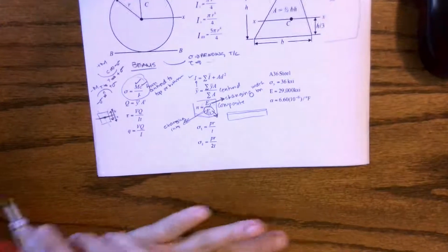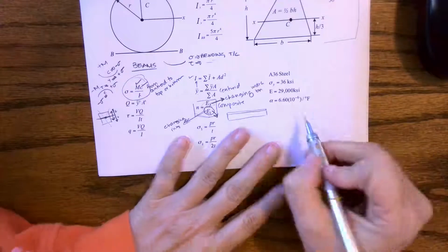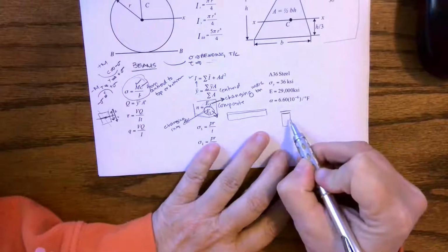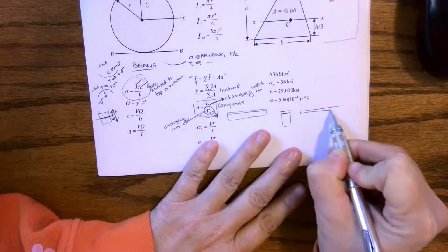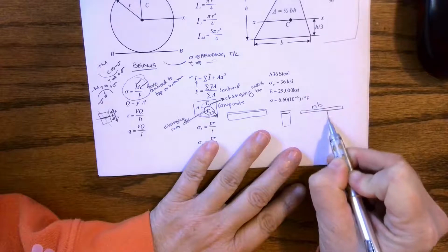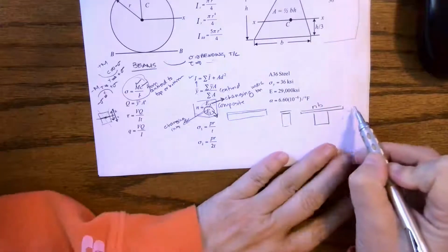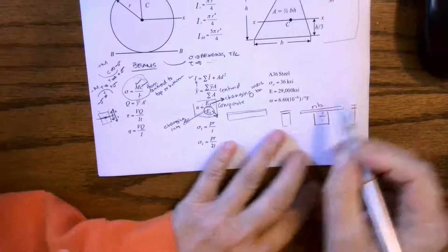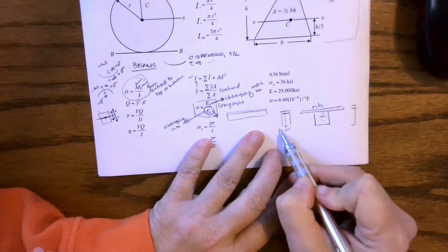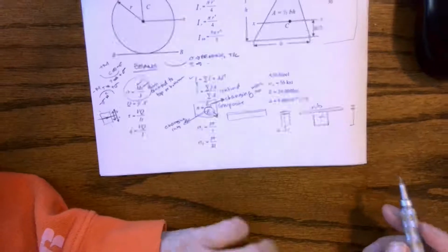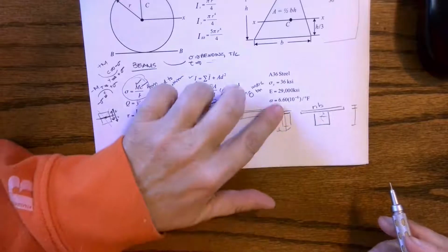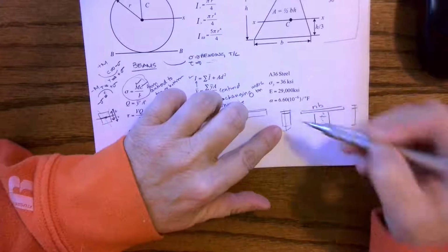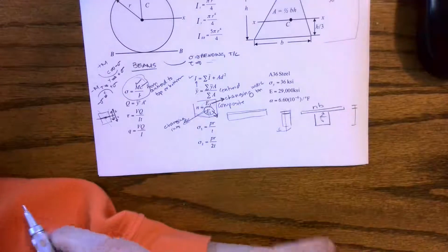When we do that, we have to draw an entirely new cross section. If this was my cross section, steel at the top is a lot stiffer than the wood, so we are going to have a new width. We are not changing the height because we have bending about this axis. If we were bending about the other axis, which we haven't looked at, it would be a whole different story. Our base is the one that changes. If we were bending this way, we would be changing the base, but we are bending about that axis.